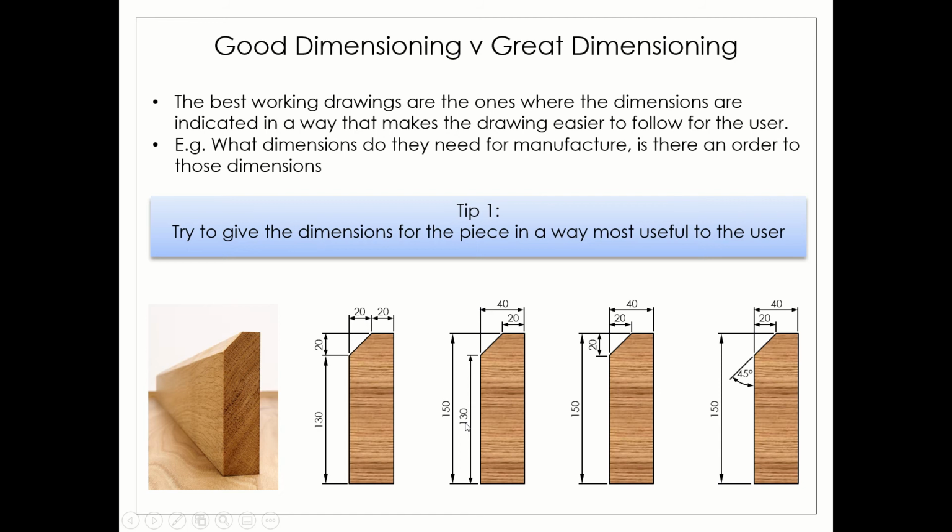And maybe that is important to you, but in this case here, that's not how you would plane a chamfer. You don't say take off a chamfer so that you have 130 and 20 left over in the piece. You dimension it more like what we have here, where you'd say 20 by 20. I'm taking a 20 by 20 chamfer.